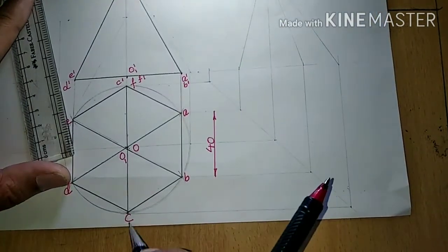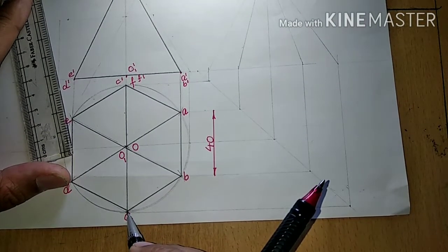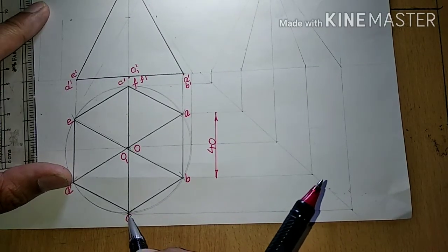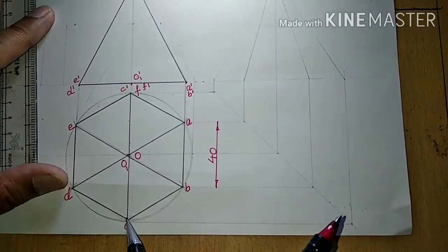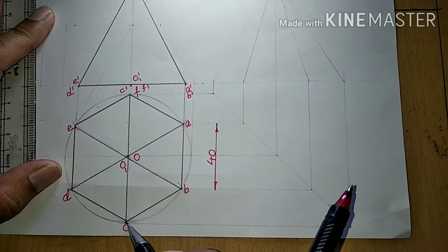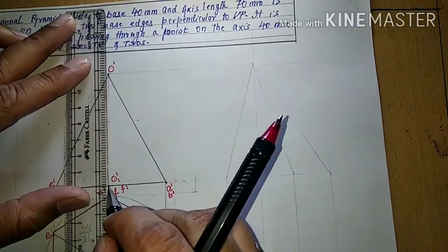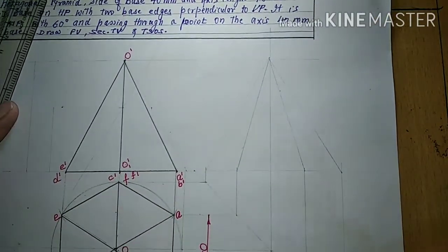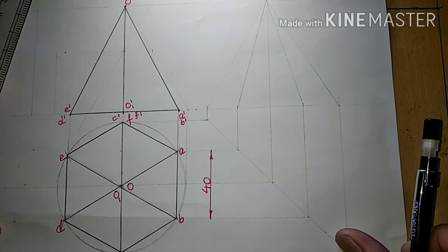From here, the observer sees this. The observer can see this particular corner, that is C. So all the three edges coming from C can be visible. So C to B, already a part of the outline. C to D, already a part of the outline. C to O can be seen, so it will be drawn by a visible line. Again, all of this is by a construction line. I am making it a little bit dark so that it is visible for you.